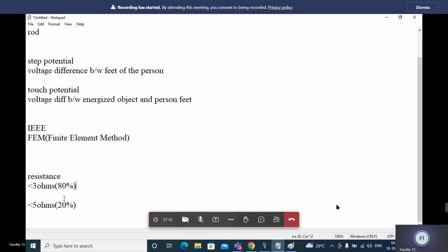Why? Because after placing the grounding, that is the conductor, the earthing mat as well as the rod, they will place coal, then soil, then salt, again soil, and then coal, salt, like that, inside the ground. After that, in between, they will put water also.